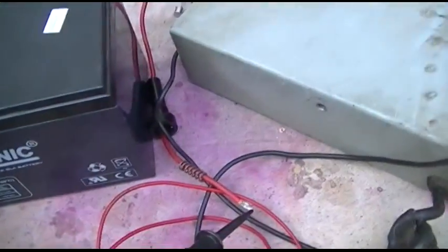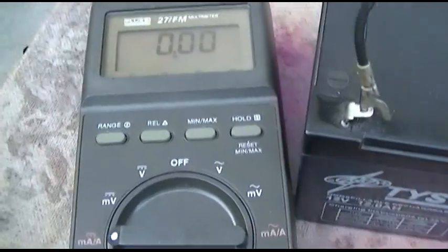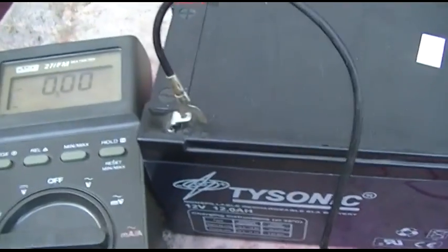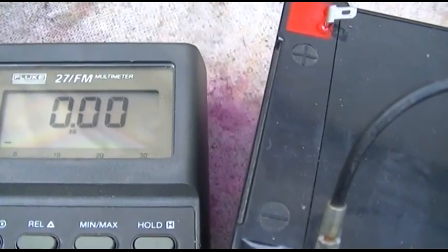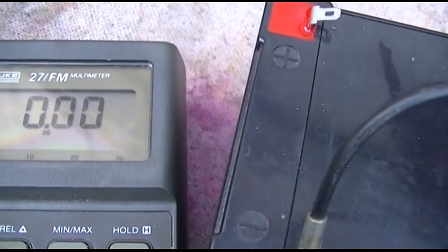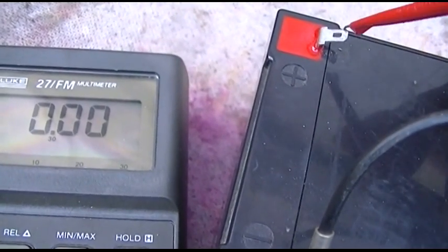And it's kind of interesting that it started out at 4 amps and then it quickly dropped down to 3 amps on the second try. When you see that you generally would think of a capacitor doing that, but I can't see a capacitor being that shorted in this unless it's a tantalum.